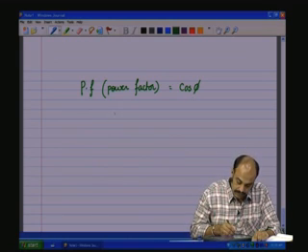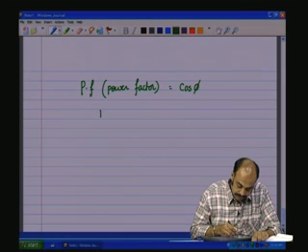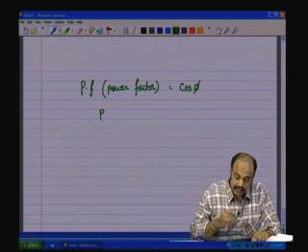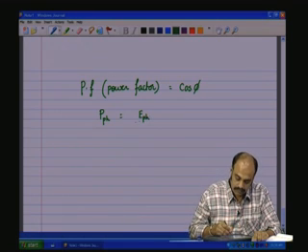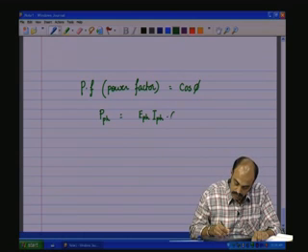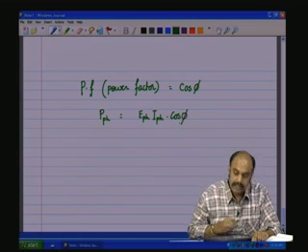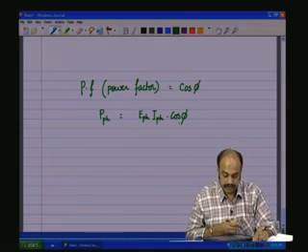So, the active power in each phase, that is per phase, will be E phase RMS value, of course, I phase RMS, these are the effective values, into cos of phi, as we had discussed earlier in a single phase circuit.